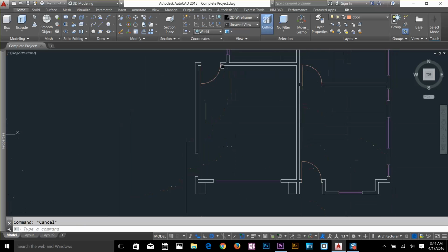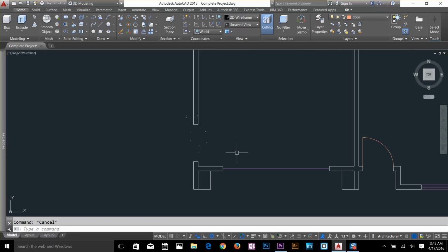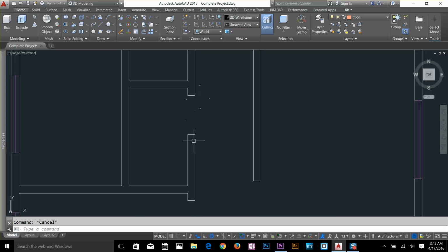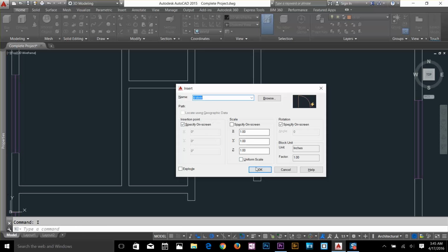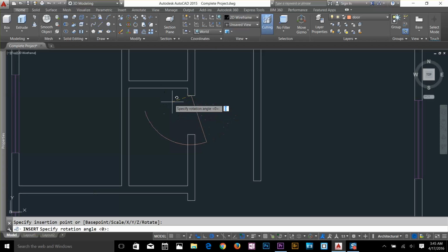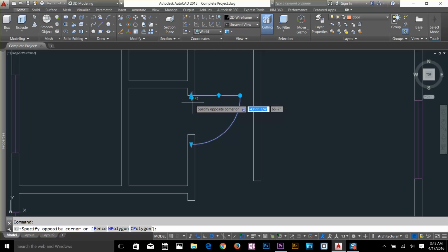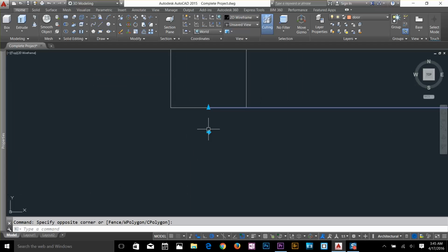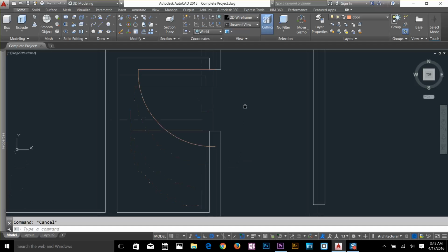And now I've got one of the doors. Let's say it's a smaller door now, so press I, spacebar, OK, and then I'm going to drop the door here. The angle would be, just leave that angle there, maybe here, and click here, and then you need to flip that door. Zoom in and then just flip it. And then for the scaling factor, click here, click this vertex, and then just drop it there. There you go guys, you got your door done.